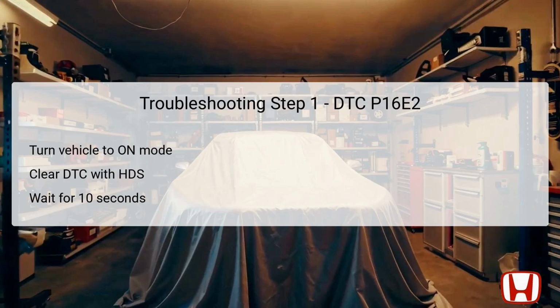The first step in troubleshooting the P16E2 DTC involves verifying the problem using the Honda Diagnostic System, HDS. Start by turning the vehicle to the on mode, which powers up the electronic systems without starting the engine. This allows for clear communication with the onboard diagnostic systems.